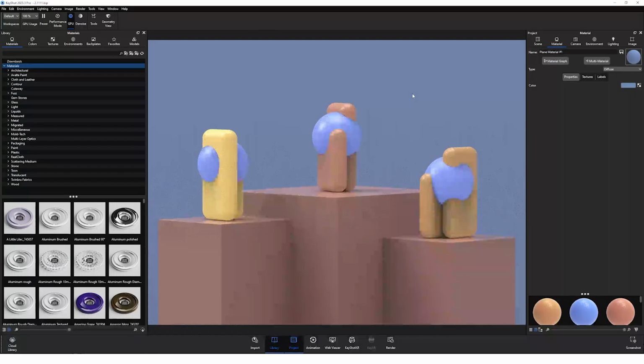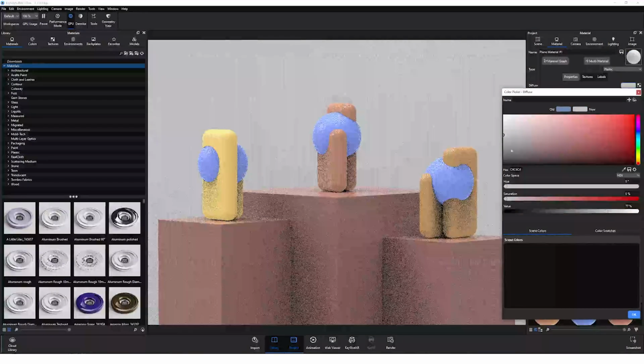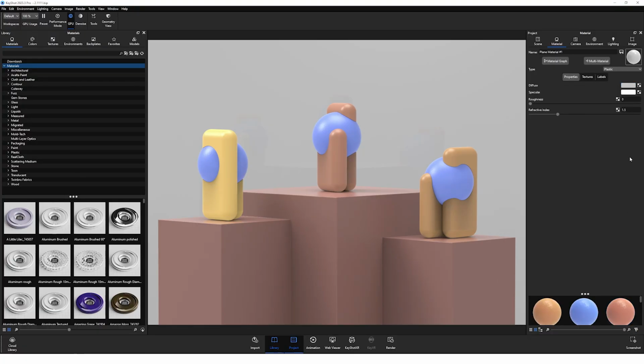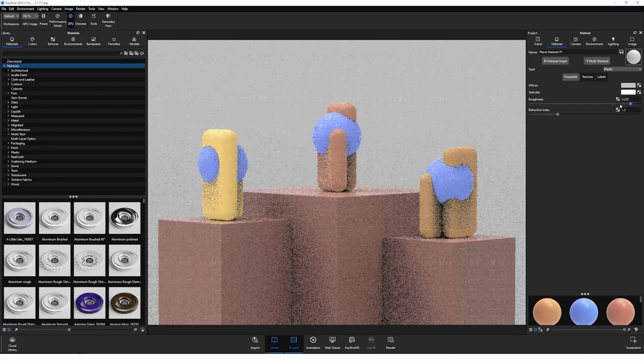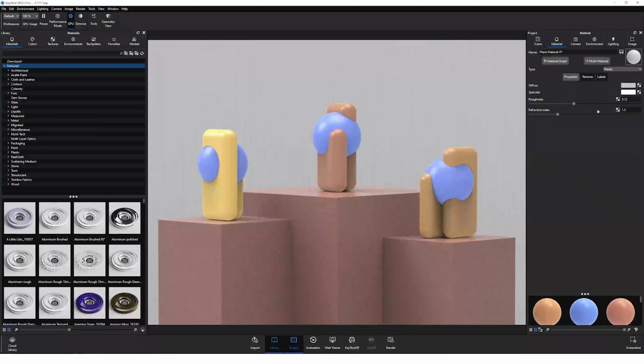Lastly, let's change the material in the back from a diffuse to a plastic and change the color to a middle gray, light gray color. This won't matter too much and we'll see why in a bit, but let's also crank the roughness all the way up. You can see if you use the slider, you might not be able to go past a certain value, and that's because everything is relative here. But this goes up to 1, and so let's change this to 0.75.